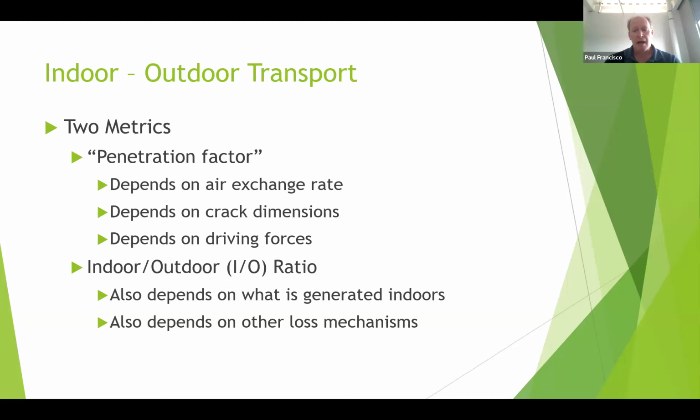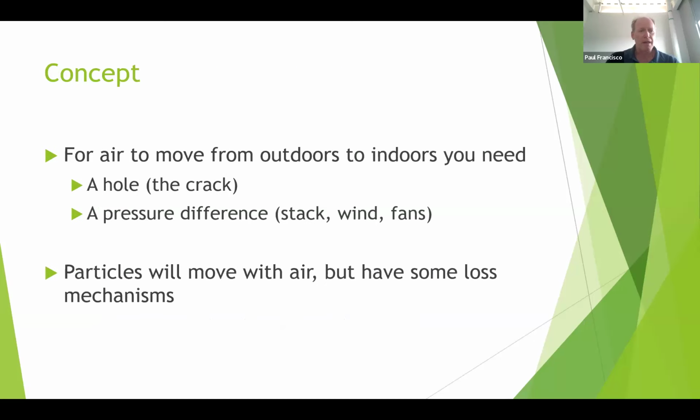It depends on how much airflow there is from outside to inside, on the dimensions of the cracks that the air is going through, and on the driving forces. The indoor-outdoor ratio still depends on the penetration factor, but it also depends on what's generated indoors and other loss mechanisms, which I'll talk about in a little bit.